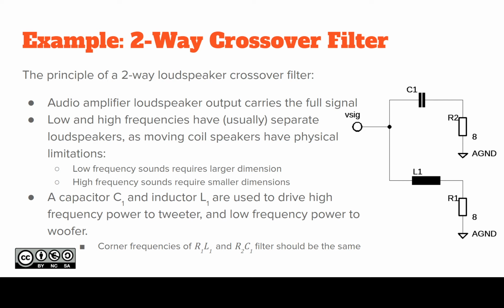So practically then we have the lower frequency woofer down at R1, and it has the inductor L1 that passes the lower frequency current but blocks higher frequencies.